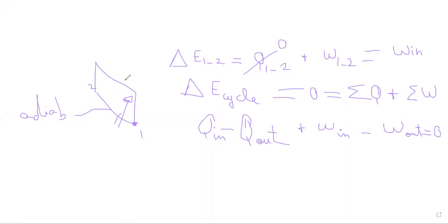Okay, we should pay attention to why in 1-2 and 3-4 we didn't consider any heat: because they told us that these compression and expansion are adiabatic processes. Now, who can tell me why between 2 and 3 and between 1 and 4 we didn't consider the work? Do we have work from 2 to 3 and from 4 to 1? Because the volume didn't change. Constant volume. Yes, very good. You know that the work is calculated as the integral of PdV, and because the volume didn't change here, during these two phases there is no work.